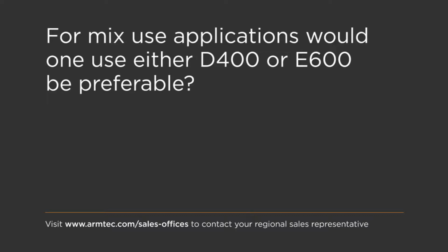Okay, I'm not sure I get the question, but yeah, D400 is of course 400 kilonewton proof load, E600 is 600, but usually in a road and street application it can be either D400 or E600. It will depend not on the traffic, because the vehicles are usually the same, but rather on the traffic pattern. So, what is the speed of the traffic? But often it's going to be E600 if it's a road application. If it's a residential road, then D400 would probably be appropriate.